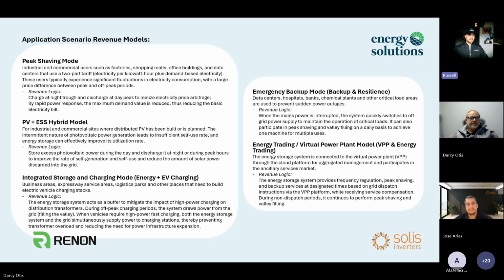That can be very directly impacted by providing energy storage that is distributed and pulled from when you're at that peak demand range. So once you hit a particular threshold, the energy storage will discharge in order to reduce the total peak that you're drawing from the grid. This is a very direct energy cost saving structure.